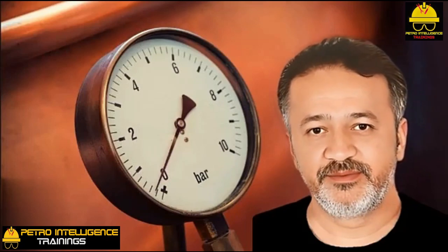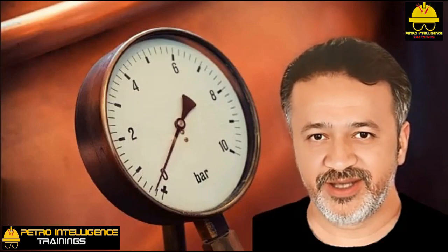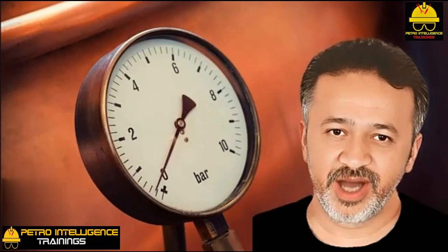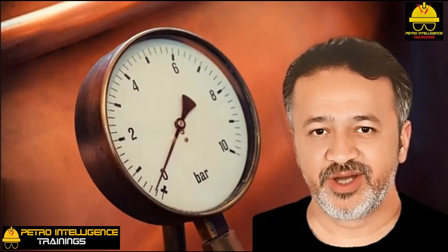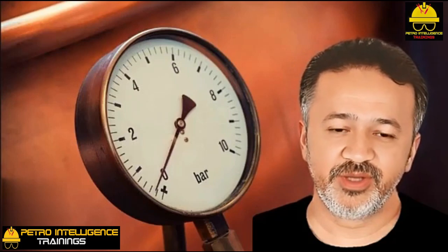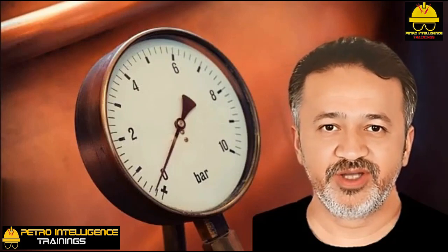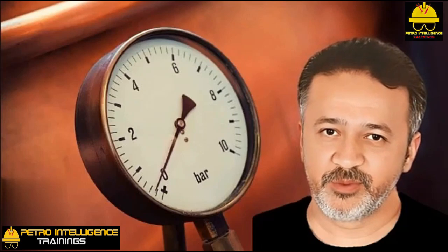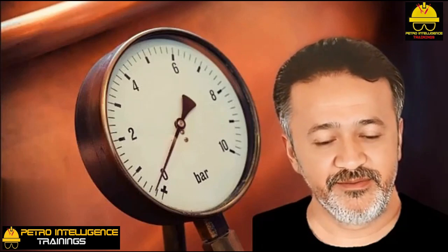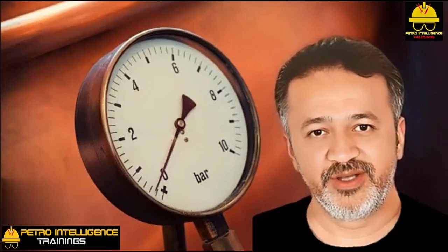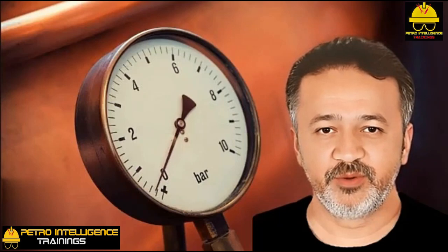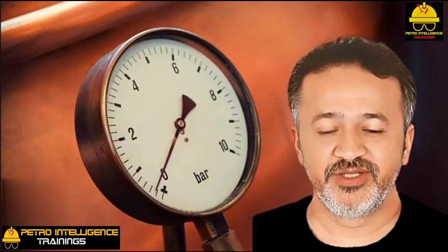It's wrong. The chief engineer failed to realize that the vacuum pressure indicator was not equipped with a barometric pressure compensator. An ordinary vacuum pressure indicator or pressure gauge reads the pressure difference between the vacuum system and atmospheric pressure. When ambient temperatures drop, the barometer rises, or ambient pressure goes up. An ordinary vacuum pressure gauge or indicator would then read an improved vacuum. But in reality, the vacuum has not changed.